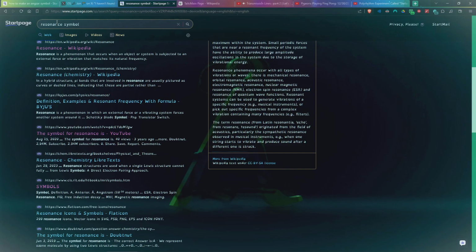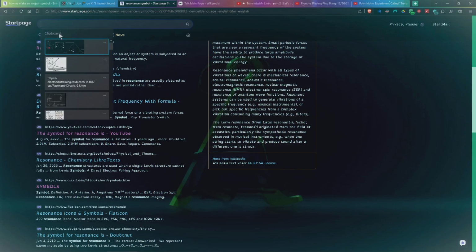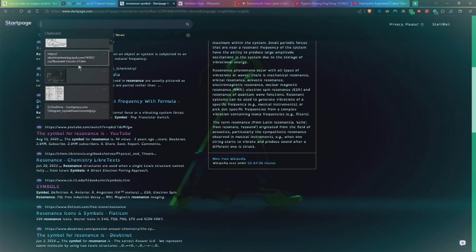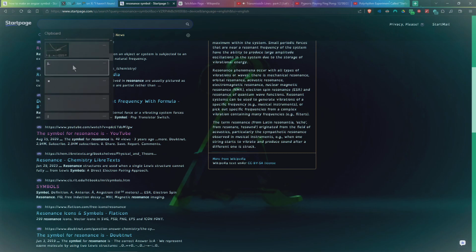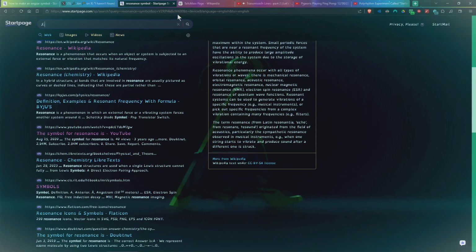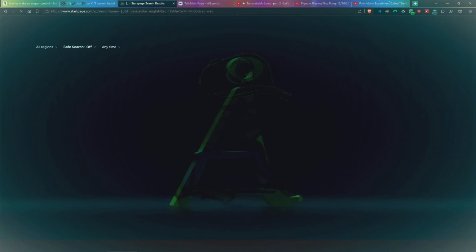And we saw that this infinite number of inductors and capacitors is equivalent to a real impedance called characteristic impedance. This impedance does not absorb power. It only establishes a relationship between the voltage wave and the current flowing in a line.